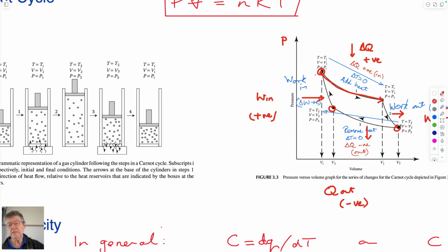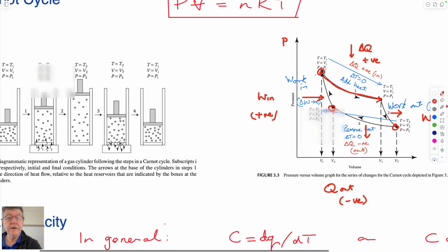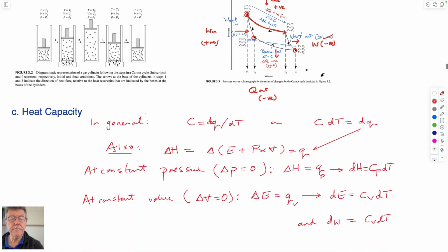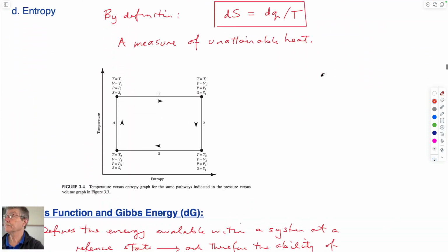So you're taking work out of the system. Then you take heat out of the steam to be able to condense it, to take it down to a smaller volume, and then you provide compression to be able to get it to the same density as it was before, as liquid water. And then you can repeat the cycle. So that's the definition of our system.